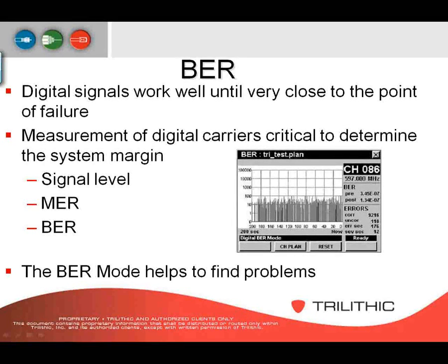So BER, like I said, a digital signal works well until very close to the point of failure. Measurements of digital carriers are critical to determine the system margin: signal level, MER, and BER. Now the BER mode helps to find the problems itself.